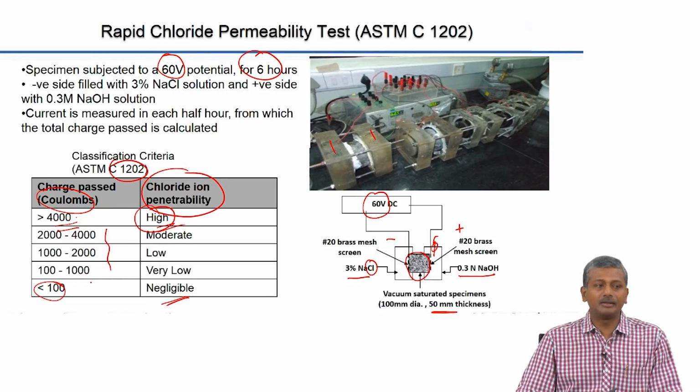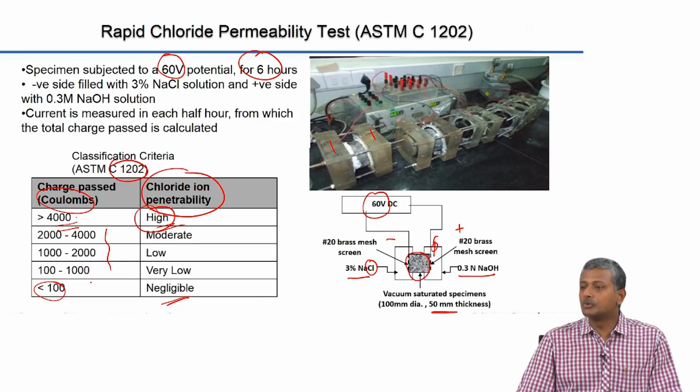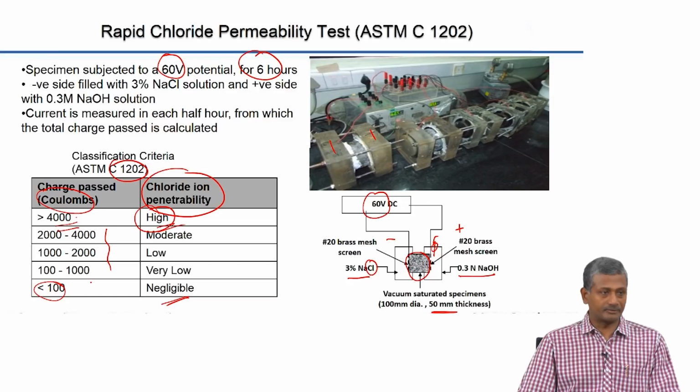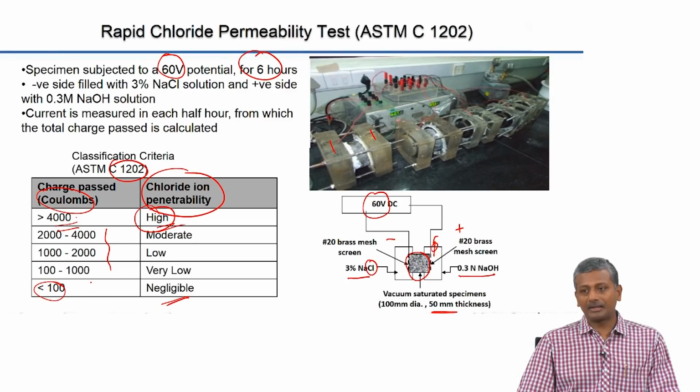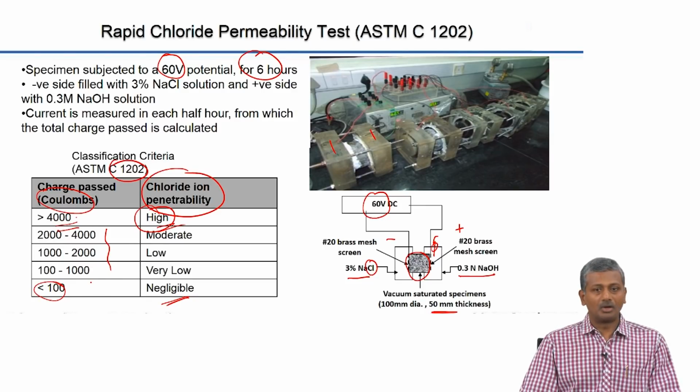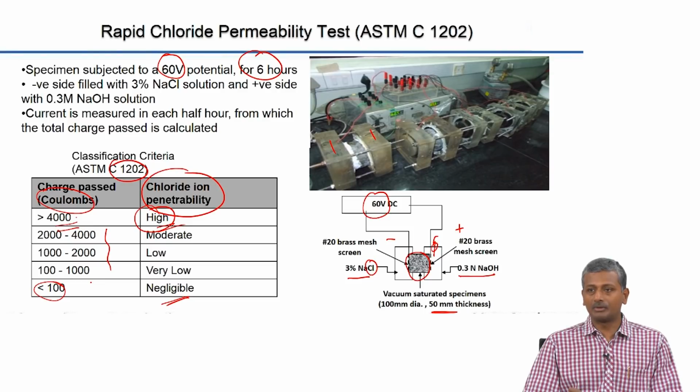Again, the basic emphasis that you need to give on this is that most of the parameters that you get out of these durability tests are not quantitative parameters, they are qualitative. So, they need to be characterized qualitatively. Okay? You do not really get a quantitative estimate of the ability of chlorides to pass through the concrete, you get a qualitative estimate of whether the concrete is good or not.